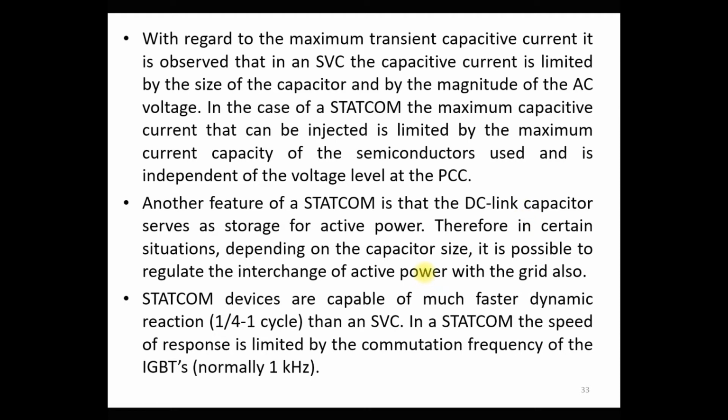In the SVC, we can interchange only the reactive power. Then STATCOM devices are capable of much faster dynamic reaction. It is in terms of one fourth to one cycle compared to the SVC. It means that the STATCOM provides a very fast dynamic response in any large disturbance conditions as compared to the